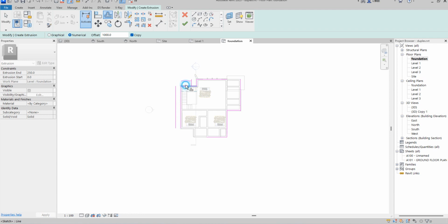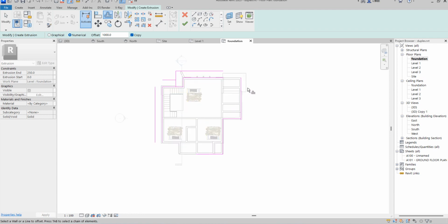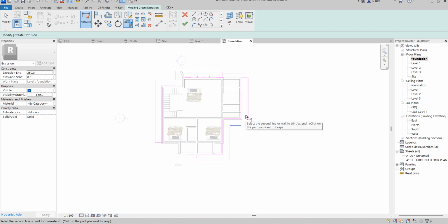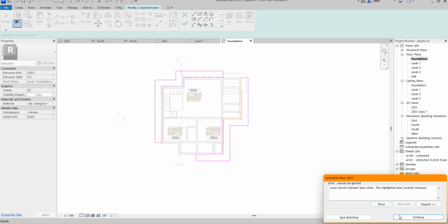So offset with copy. So what you do now, you close the gap, that is the edge gap. Okay, I think with that you close this one so that you trim the remaining parts that look open, because that open side is not what Revit wants. So you must always do your best to close it up.